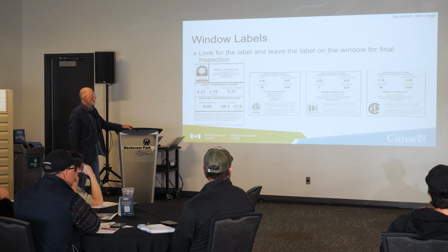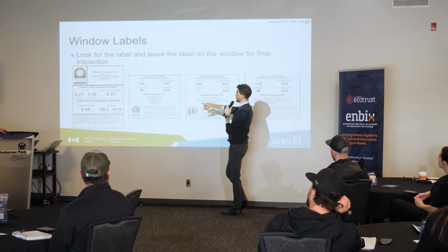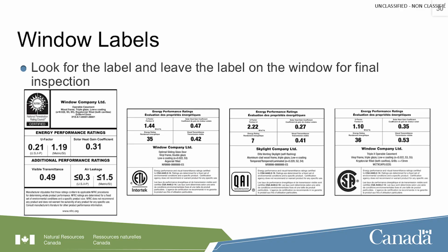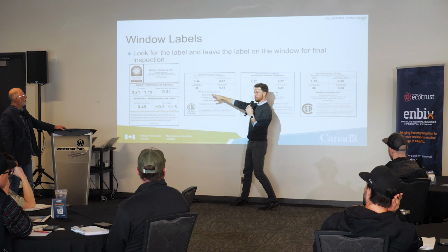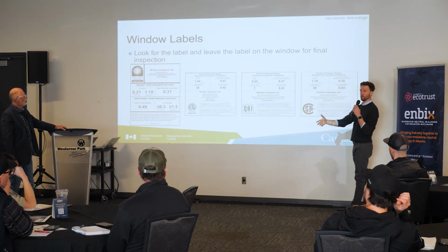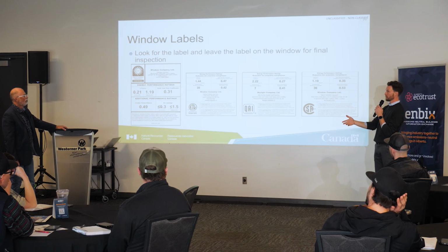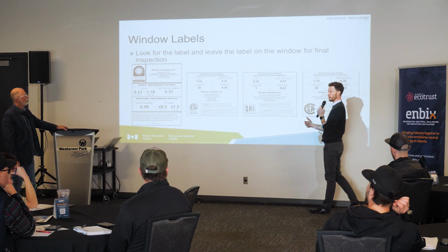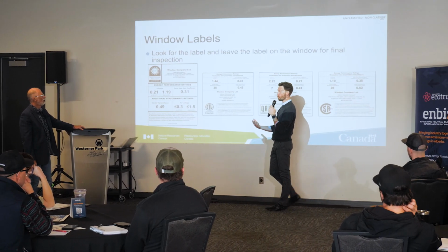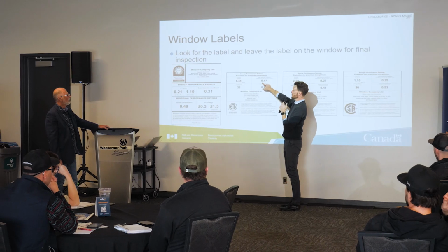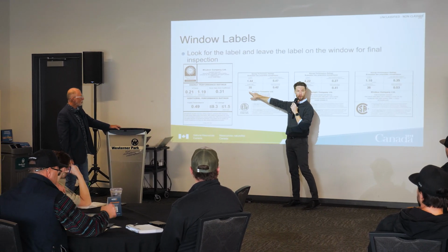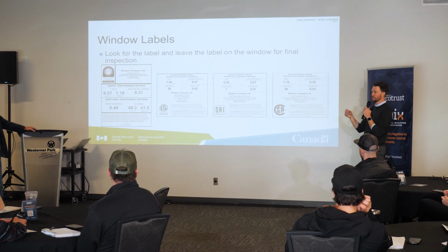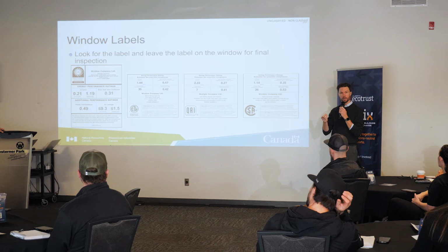Go ahead, Mark. I love this slide, because this is a really great example of understanding which number you're using to make your decisions. This is a very excellent energy rating score and a very good window if your heating season performance is your primary concern, right? But if you're worried about your homeowner cooking because you're choosing big windows and you're in a warm location, I'd be more worried about this number than this number. So they don't all tell the same story. They're each giving you a different perspective on the performance of that window.